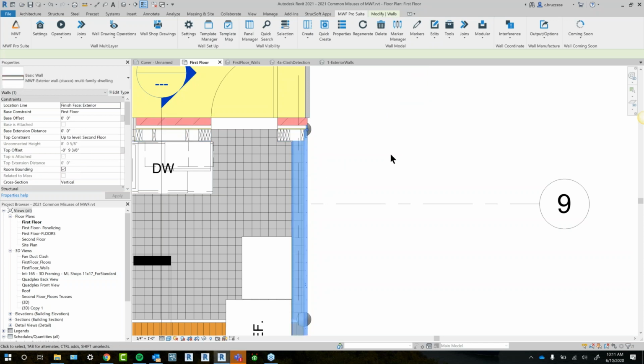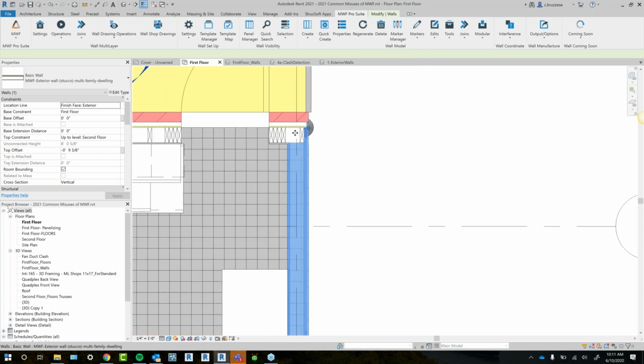Depending on which way you're going about framing your panels, if you are just using the splits as is and keeping the Revit wall whole, then you'll generally want to place the joins beforehand before you even start creating the splits, and I'll explain why.